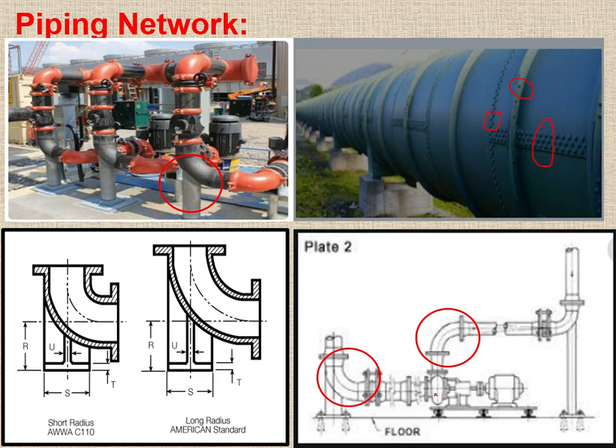Okay, because whenever the pump discharges water through this point, there is a strong force exerted here. So if you do not provide a strong support, what will happen? It may bulge or move right and left and may damage. Okay, so we provide an anchoring force at this point. So how strong is this anchoring force supposed to be? We have just seen how we can calculate this anchoring force. Okay, so these are the nuts and bolts also.